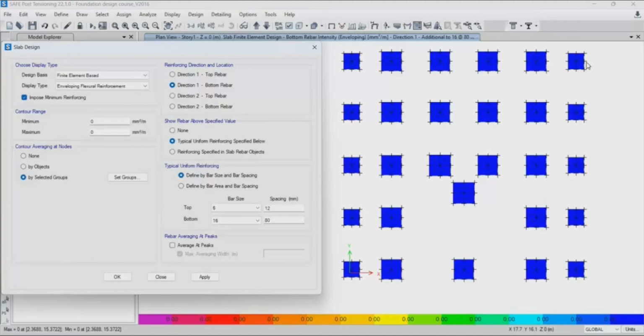Because you know that when you push down on an isolated footing, let's say you push down on this isolated footing, the stress is going to spread into the soil in a shape that we call a pressure bulb. We are going to have a pressure bulb for this isolated footing. Now, if these two large isolated footings are spaced very closely together, then the pressure bulb of this footing and the pressure bulb of this other footing are going to overlap, right? They are going to be overlapping deep underground. So this is going to double the stress on the deep soil layer, which can cause severe and unpredictable settlement issues.